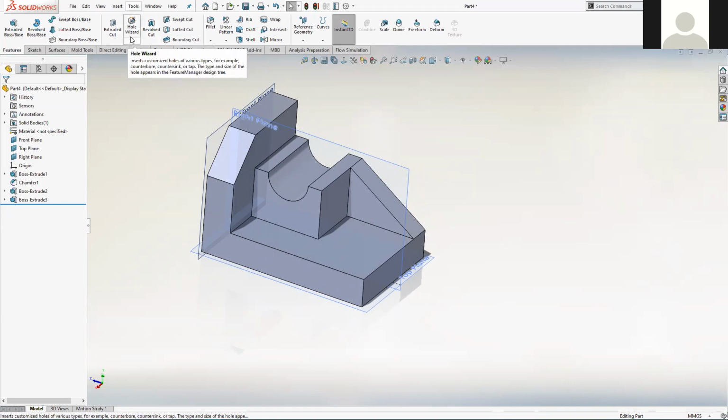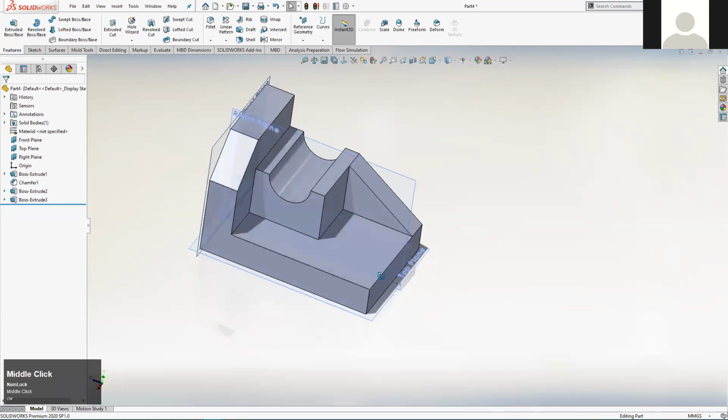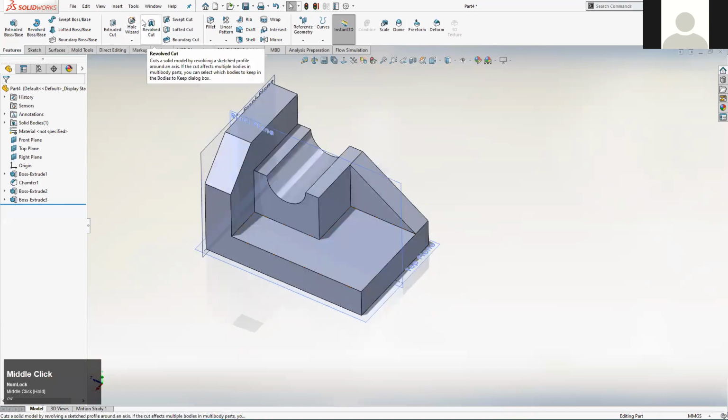So you would go in there and say, right, I want a BSI hole, BSI being another standard in there, and I want it to be tapped, and I want it to be M6, standard coarse M6 hole. So the system has all the spec to do with that already stored in there. But the Hole Wizard also stores standard slot sizes as well, so we could use that. But for what we're trying to do here, I think that's a little bit overkill.